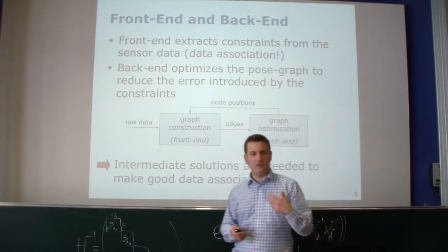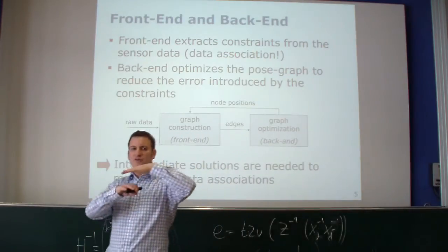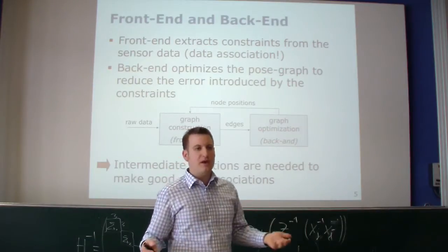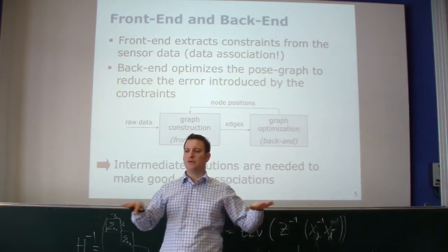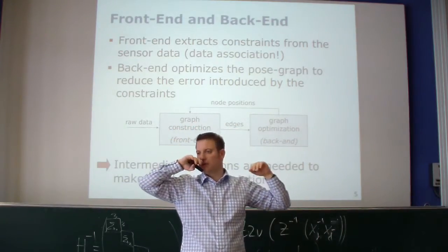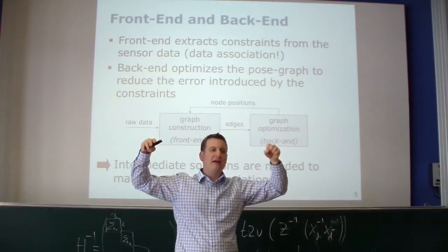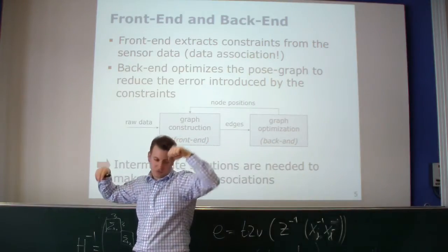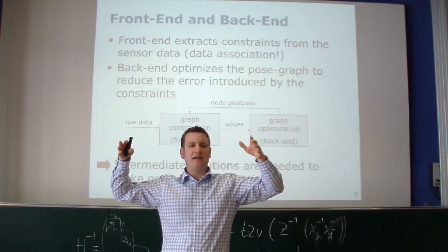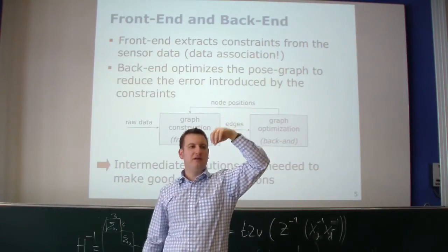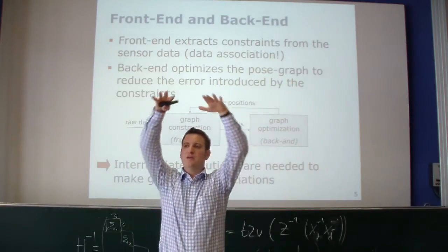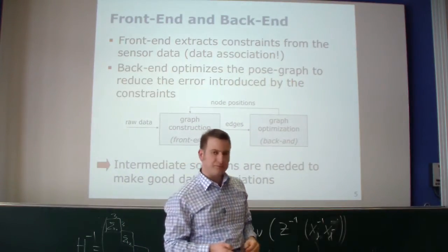The idea here is to not use a single pose graph, but to use a hierarchy of pose graphs. So we use the pose graph we have so far, what we call the lowest level, and then build sparser representations of that pose graph on the higher levels. On the higher level, we have a node which corresponds to one of the nodes of the lower level, but there are much fewer nodes. One node in the higher level represents a whole group of nodes on the lower level. And I can build that up as a hierarchical graph.